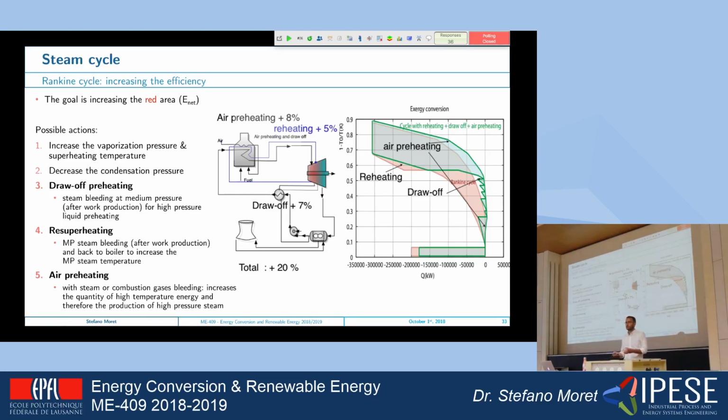And here, of course, you have a trade-off between the cost of doing all these modifications to the cycle, which means having a more complicated system, having a regenerator, having more heat exchangers, and the gain in efficiency that you have. Normally, real cycles in real applications have almost all of these enhancements because it's worth doing them.